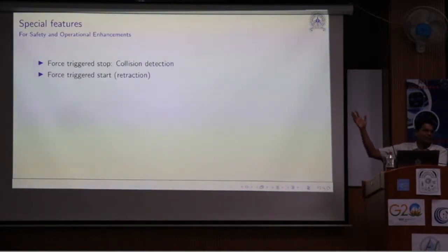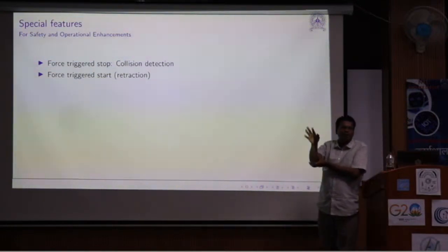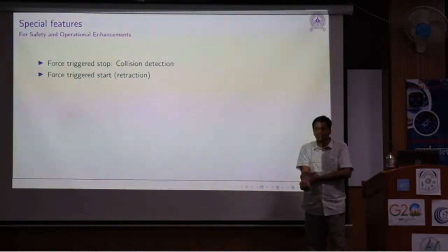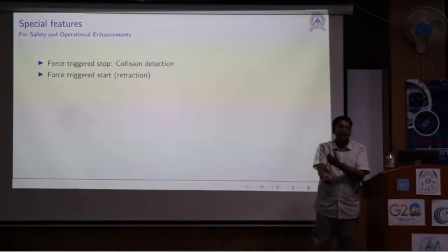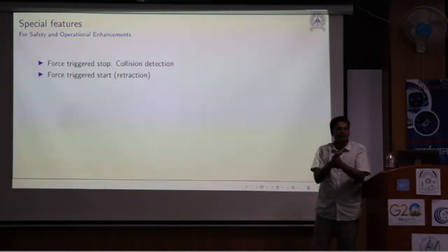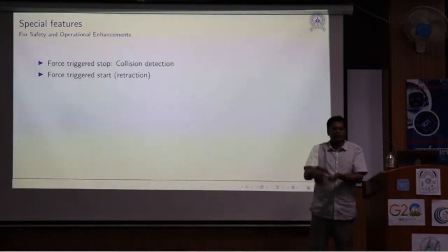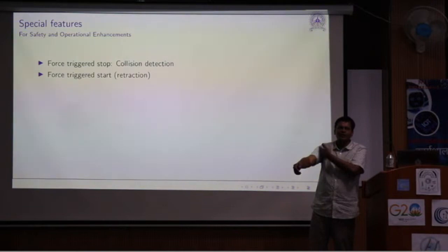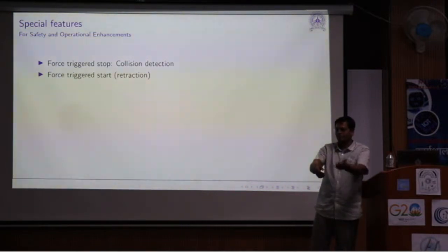You saw the joint architecture. There was no vibration sensor in between. You have a torque sensor at the joint. Right? So at these joints, if you tap, that torque variation will come, no? That will let you know which link you are tapping. If you are tapping it twice, in this link or whatever link, accordingly the torque sensors will show up, right?